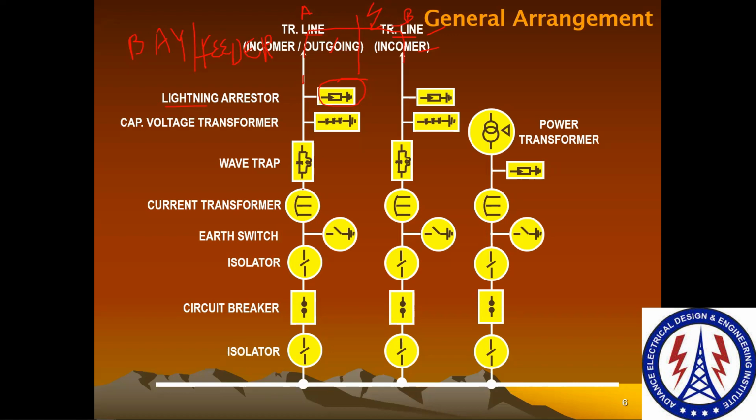All the equipment downstream is sized for a particular value, and this charge is very high if you calculate it. So when it strikes and enters the substation, our complete substation may become unhealthy, insulation may burn, or anything can happen. For that reason we put a lightning arrestor.